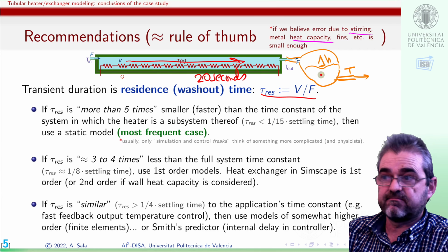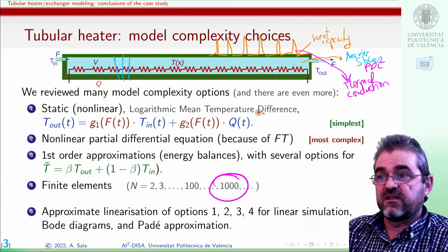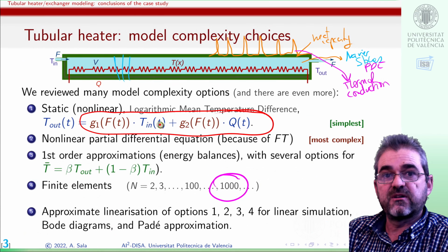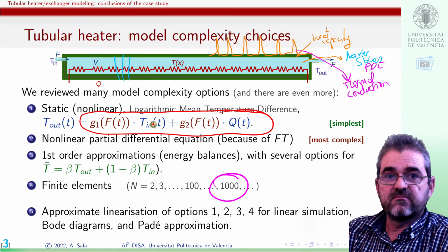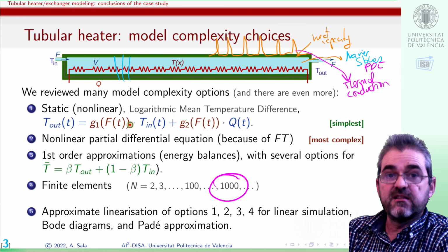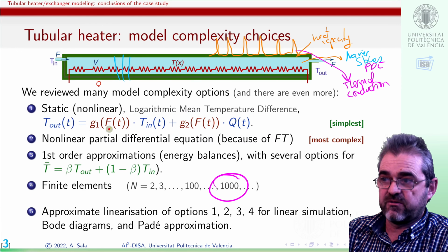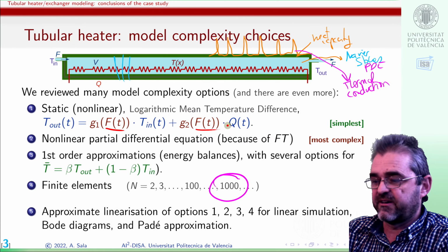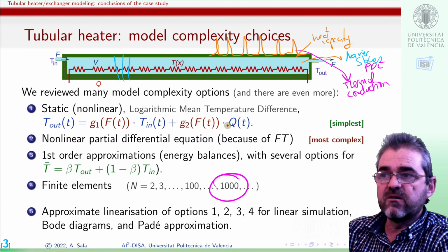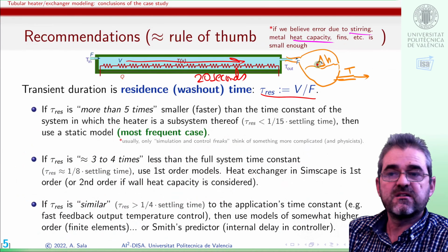So in that case, I would use just the static model, saying that, okay, each kilowatt hits 12 degrees, and due to thermal losses, inlet temperature increments get multiplied by 0.9. So that kind of proportionalities, maybe, taking into account possible flow variations. Then, as I said, that kind of proportionalities will be the only thing to be used in this 1 hour of mixing application.